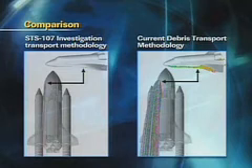And to kind of give you an idea about how much work was involved in that, we have 16 major debris cases we run. We've got about 155 identified sources of debris during ascent, but they break down into approximately 20 classes. About 16 of them we run in this simulation. And we run about 10 million cases of releasing debris into the flow field for each one of these cases in order to cover all of the initial conditions, all of the locations the debris can come from, the range of possible velocities that could come off, the direction that it could possibly fly. So in our basic analysis set, we have about 160 million cases we run.